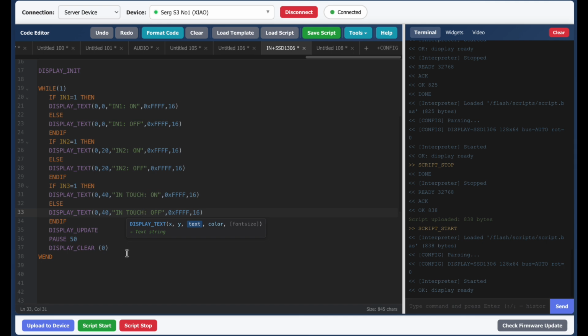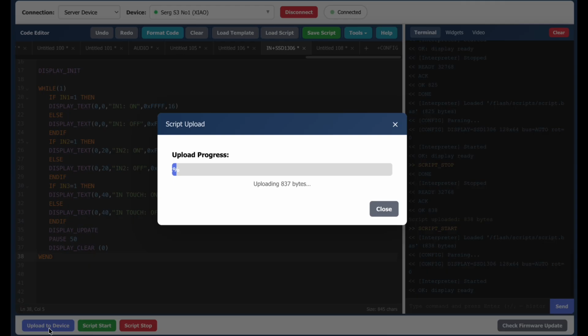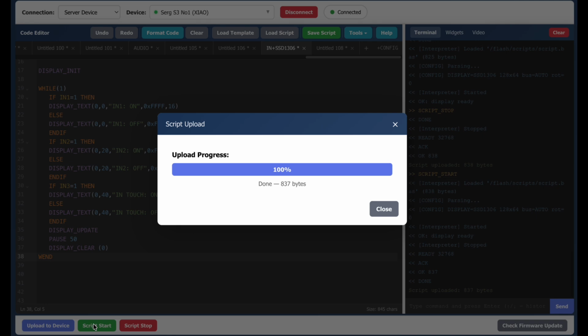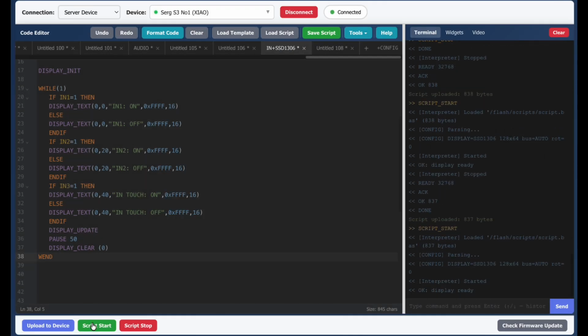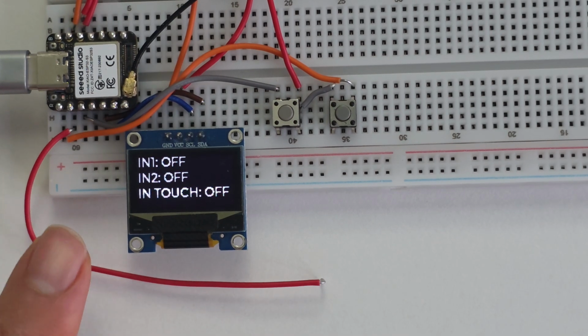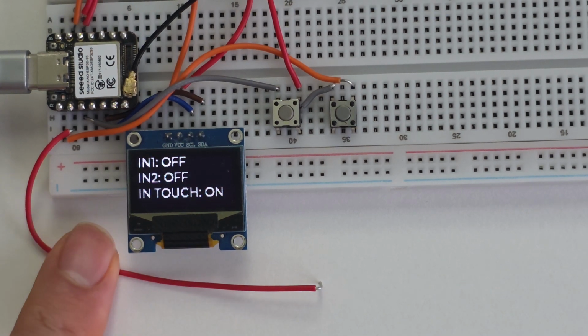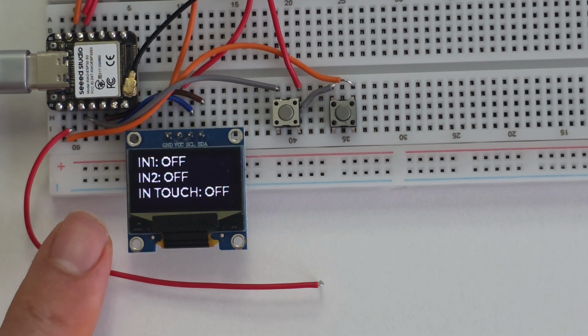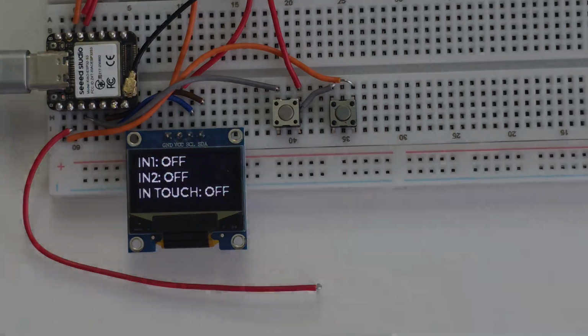This opens up some interesting design possibilities. Touch zones built right into the device enclosure with no visible buttons at all. The input returns 1 when a touch is detected and 0 when there's none. In practice, it's a button with no moving parts, no contact bounce, and no holes in the enclosure. Let's see how simple and responsive this is in real use.